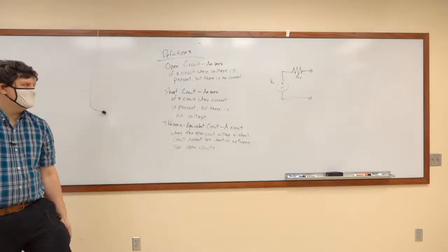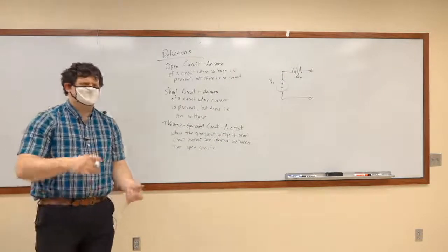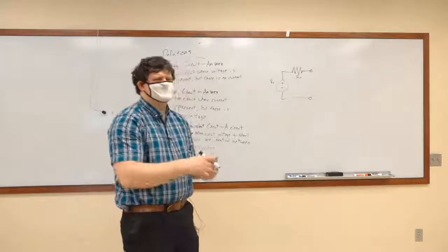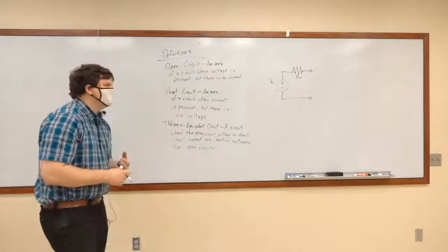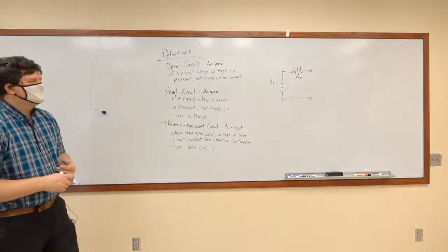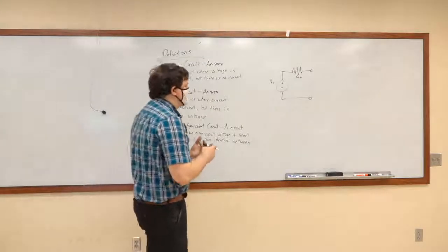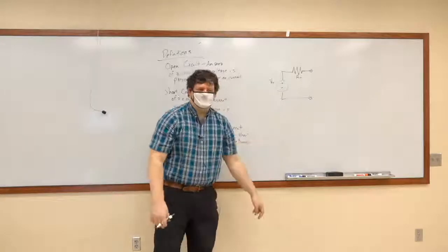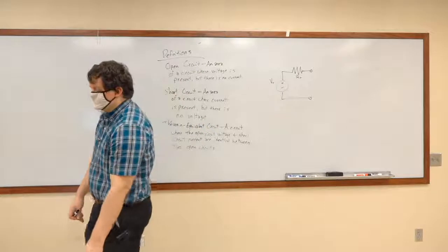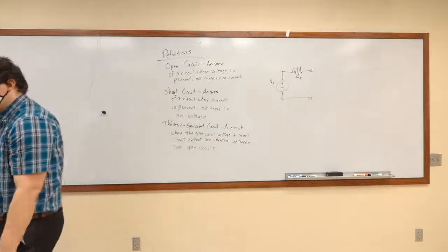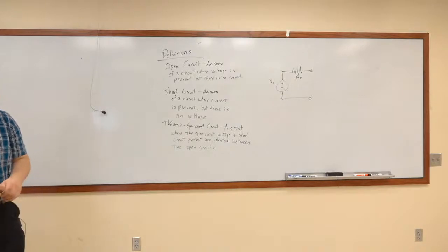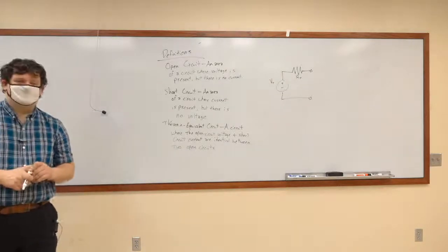Okay, and we have combined all of the voltage sources, all of the current sources, all of the resistances, everything, we've put them together into just one resistor and one voltage source, and nothing else matters. This uses the same principle as equivalent resistances, but it applies that also to now equivalent power sources.